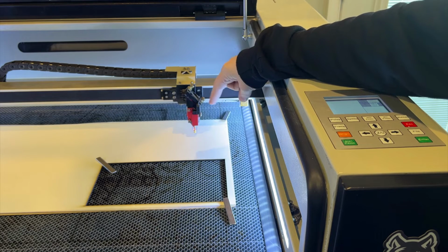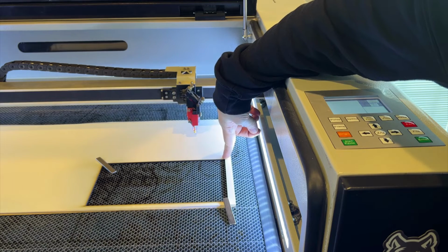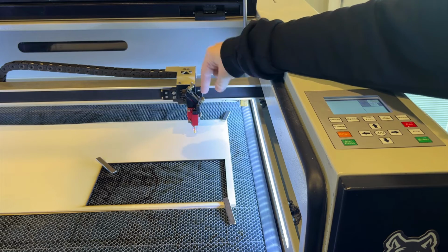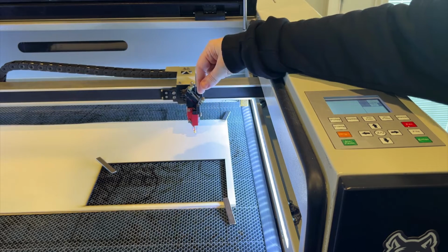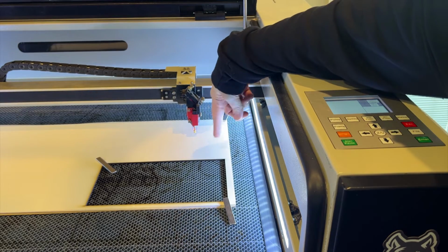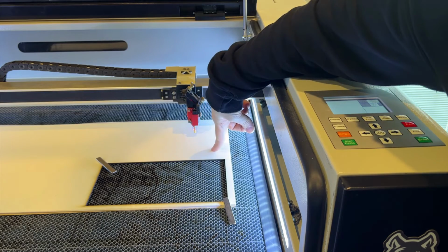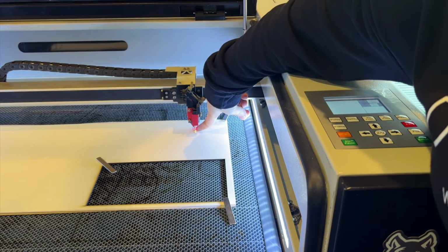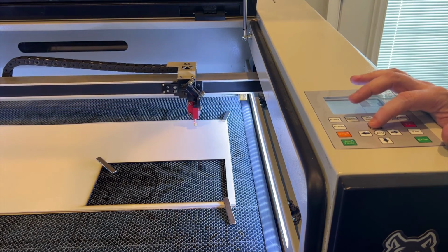What I do is sometimes for engraves, I will manually lower the bed in LightBurn by 2 millimeters so that the beam is out of focus, and I use that for engraves. But I like doing that in LightBurn because then it will automatically bring the bed back up to the focal point for laser cutting. So now that we have the calipered measurement on here and we're in focus, we can move this red dot to where we want the job to start on the laser. So I'm going to start this up in the corner.